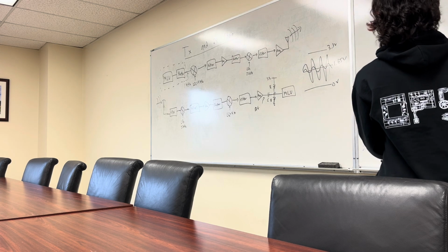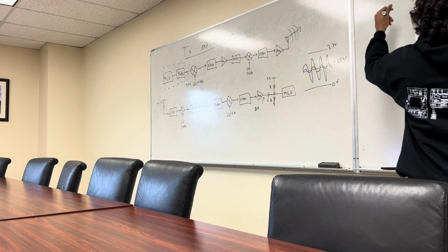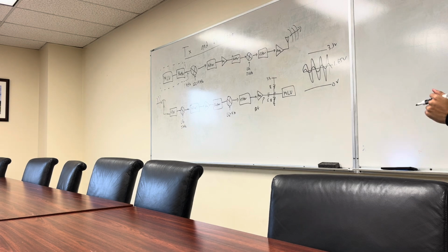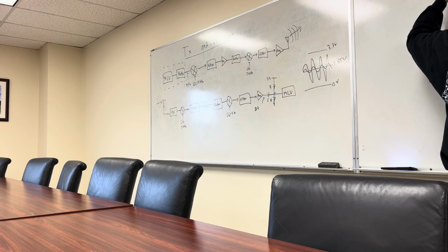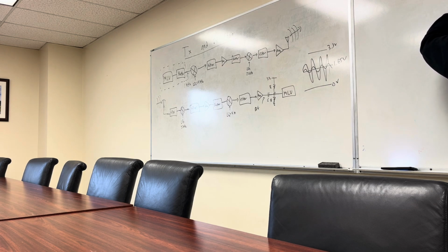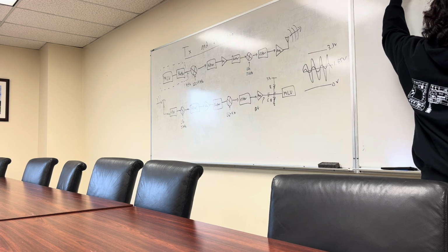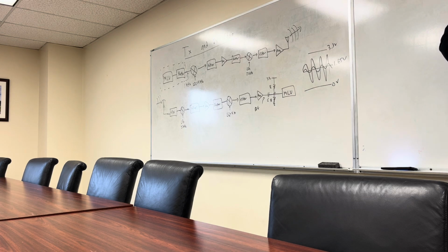So there are a few things here that we're going to talk about. If you remember from the mixer module, we modeled our MCU over there, and that buffer just has a 1 megahertz signal, right? So we fed in our LO, 4 megahertz, and then we fed in some 1 megahertz signal. This was 1 millivolt, and this we set around 0.7, 0.8 volts, right? So let me get some output.